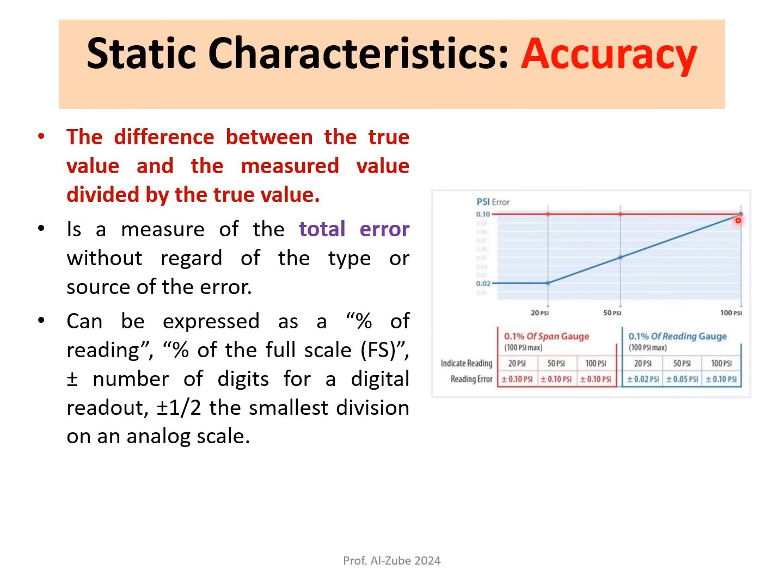So you can put your device on two modes. You can say that I'm going to be measuring an entire range. For example, this is the pressure, and I can measure from 0 to 100 psi. If you use that setup for your device, you will have a collective error of 0.1%, or an accuracy of 0.1%.